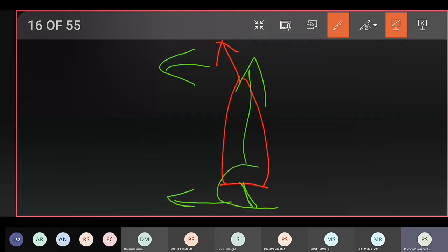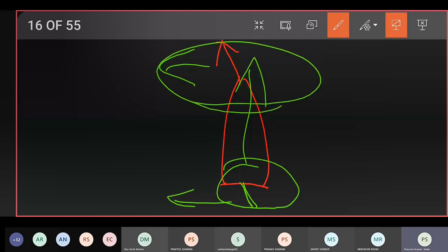Integral control is responsible for this permanent helm. So 2 degree, 3 degree, 4 degree जो भी है, which is necessary to control the constant movement of the heading to the other side, is controlled by the permanent helm.